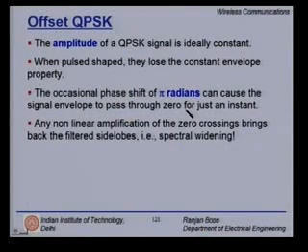But what is happening is, because of the pulse shaping, you are just forcing the 0 crossings to go to smaller values, and when you have to do a non-linear amplification of the 0 crossings, you have again the side lobes appearing. In effect, you are causing spectral whitening. You are defeating the purpose of cosine filtering or any of the pulse shaping techniques.